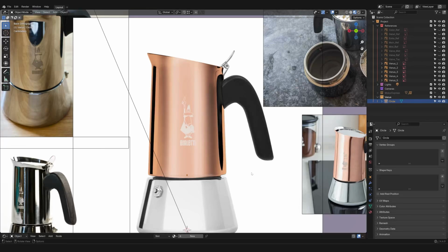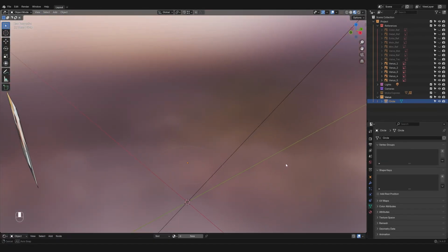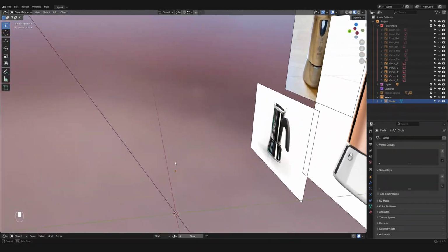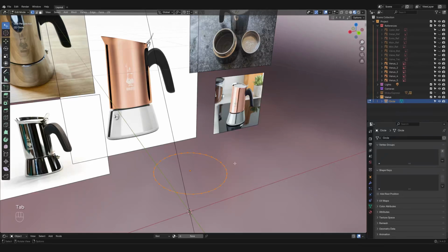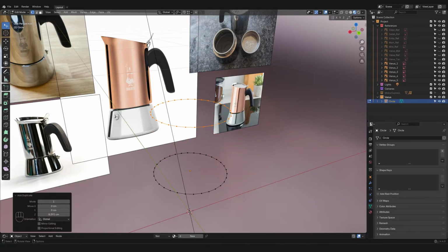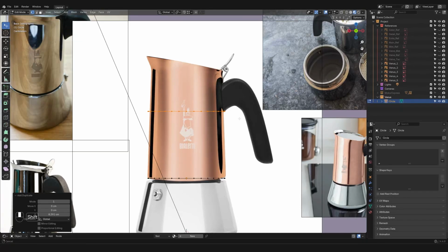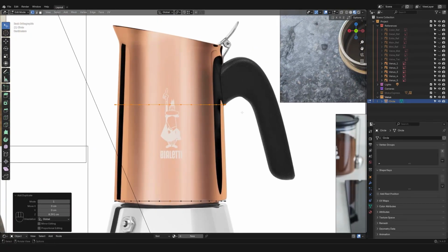Today, the way that I think I'm gonna go about this is the following. I have now created a circle for myself, and we just said that things are modular in Blender. So I'm gonna go into edit mode. I'm gonna press Shift+D, which is to duplicate, and I believe we talked about it in video 17. And then I'm gonna press Z to bring up the duplicated edge loop, the duplicated circle. And now I have a copy of that circle that has the same exact number of vertices and edges.